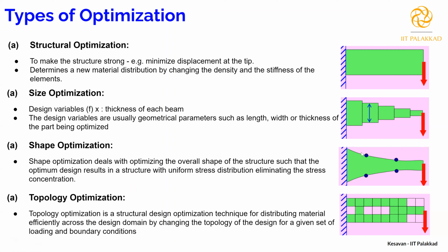Even after having this, just look at the third image, what I'm pointing at with my cursor. I don't have to have this kind of feature. So I still have the option of reducing the material. I'm removing the material at the interior. Wherever there is no load sharing or there are no stresses involved, I still have an option to remove those materials. That's called topology optimization.